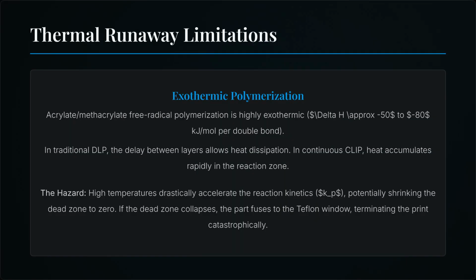Thermal management is also critical. Photopolymerization is exothermic, and in continuous printing, heat can accumulate, potentially collapsing the dead zone and causing a catastrophic print failure.